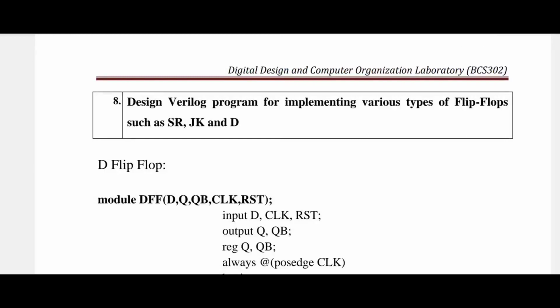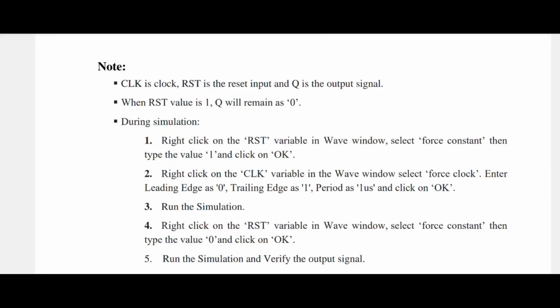And the Lab 8 question is to design a Verilog program for implementing various types of flip-flops such as SR, JK and D. CLK is the clock. RST is the reset input and Q is the output signal.